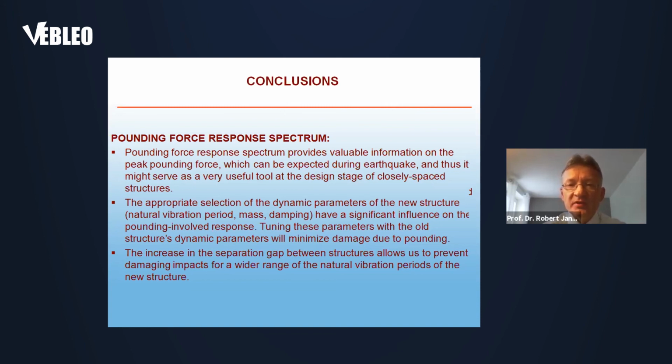Tuning those parameters with the old structure's dynamic parameters will minimize damage due to pounding. Of course, in not all cases will it be possible to do it. An increase in the separation gap between structures allows us to prevent damaging impacts for a wider range of the natural vibration period of the new structure.